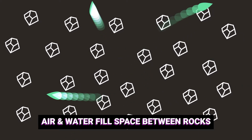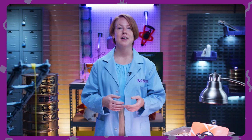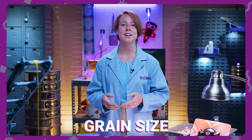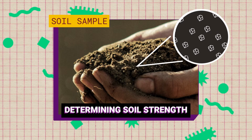mineral and organic matter. It's the composition of soil, or the arrangement of mineral matter, organic matter, air, and water that leads to a site having either a naturally strong or weak foundation to build upon. That is why it's so important to study. Soil is classified in many ways, but the most common way is by grain size. Geotechnical engineers use soil profiles to determine the strength of the soil that they are building upon.